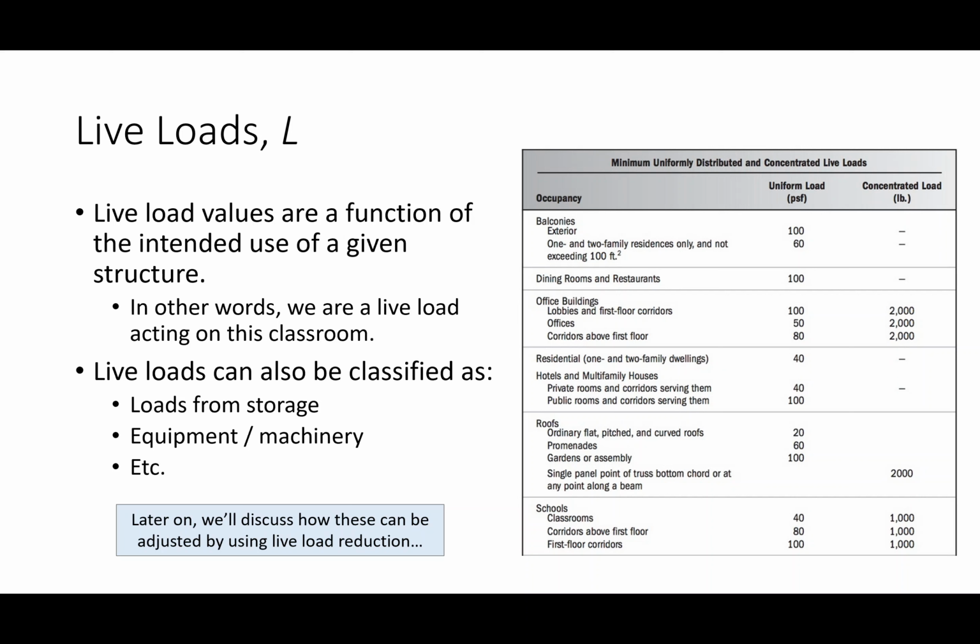But what you don't want is to be hampered by, well, these can only be hallways and these can only be offices. You want to be able to cordon that space out however makes sense, you know? So if you're an engineer designing a commercial spec office building, it's not that uncommon to size the whole floor as if it was one big hallway, because you don't know how it's going to be arranged, right? So I just throw that out there as some differences in how the designs work.